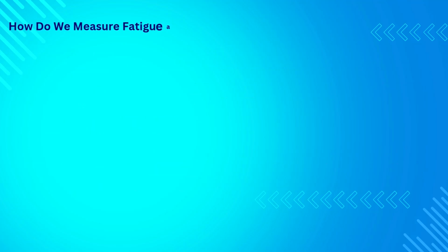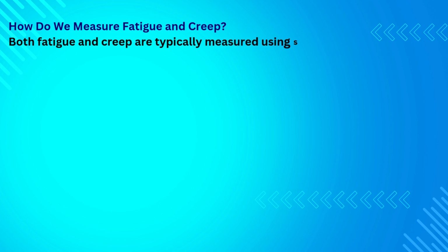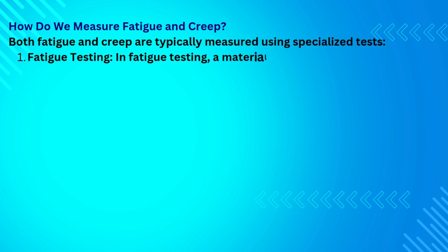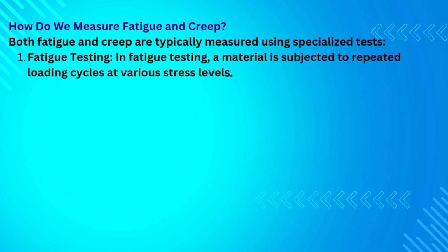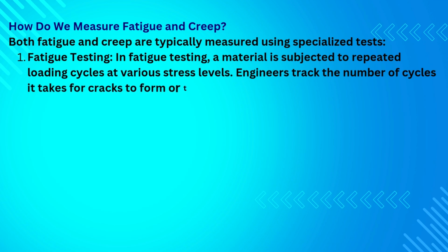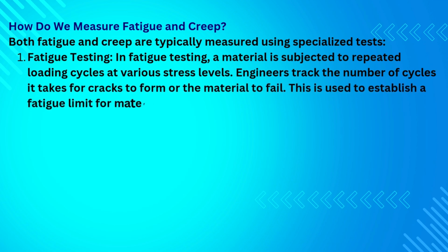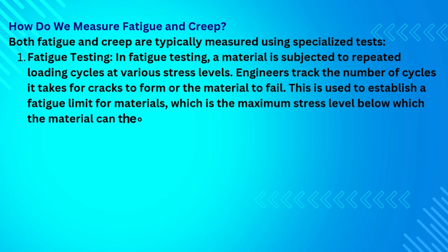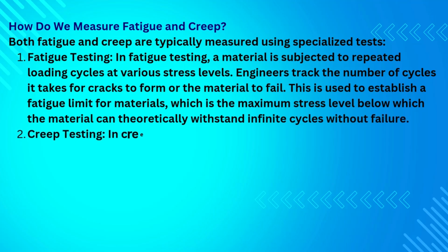How do we measure fatigue and creep? Both fatigue and creep are typically measured using specialized tests. 1. Fatigue testing. In fatigue testing, a material is subjected to repeated loading cycles at various stress levels. Engineers track the number of cycles it takes for cracks to form or the material to fail. This is used to establish a fatigue limit for materials, which is the maximum stress level below which the material can theoretically withstand infinite cycles without failure.